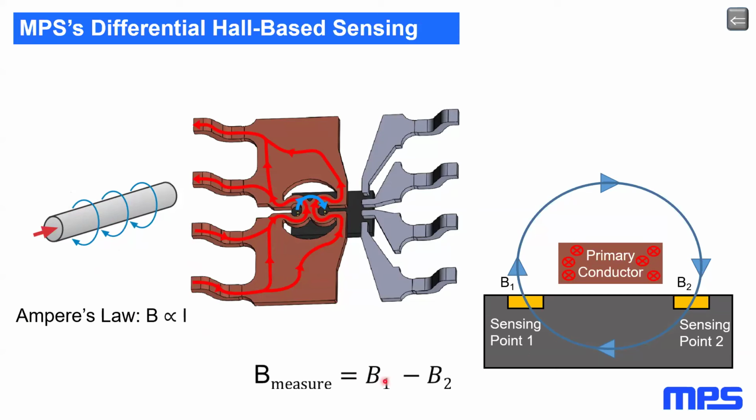And so, for example, in our MCS 1806, 1805, this is an SOIC8 sensor. So our SOIC8 sensor has a primary lead frame and a secondary lead frame. They're the same material. I colored them differently here just to show the primary versus the secondary. And what you have is current flowing in through 2 pins on the primary and out through 2 pins on the opposite side of the primary.